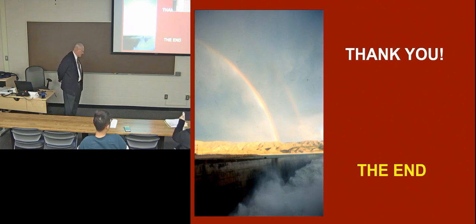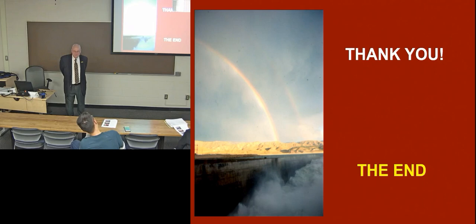Tarbela was constructed. All 4 tunnels are directed towards electricity generation now. A new tunnel had to be built on the left bank for irrigation releases. The reservoir is about 3/4 silted full. It still works fine for electric production because you have the drop in head, but it no longer functions very well for flood control. It does help a little bit for irrigation water.